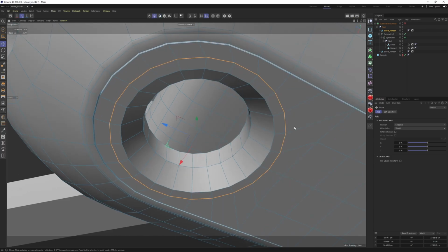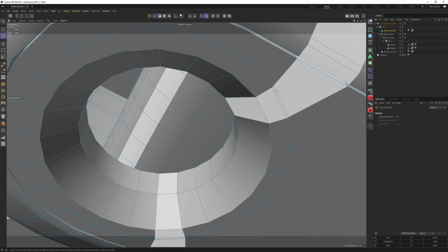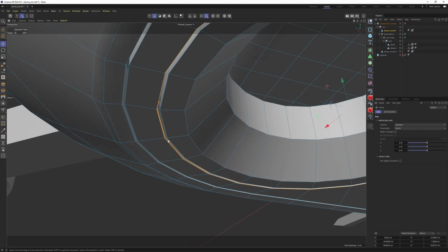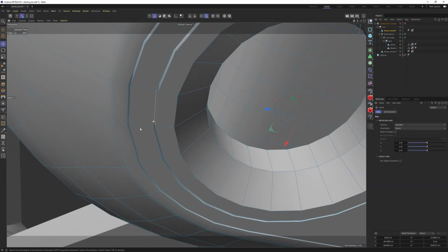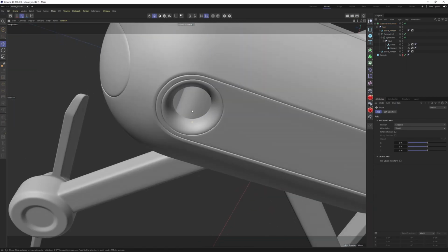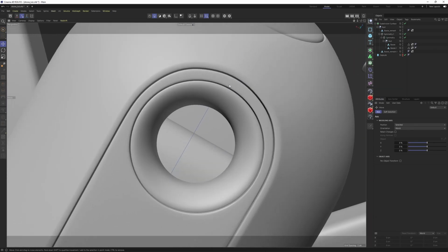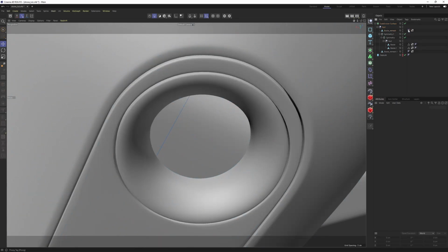I will double click on these edges, hold down control, slide these edges, polygon mode, select these with loop selection, hold down control, again, extrude them twice. One is for these edges and the second extrusion will be the end. Now hit Q and see what's going on. Okay, looking perfect. Again, we can play with this Phong angle to smooth some of the parts.